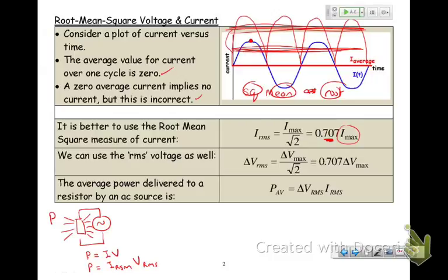that works. So what happens, frankly, is you get used to being able to treat AC circuits like DC circuits as long as you use the RMS values. So you can do a simple circuit with a whole bunch of resistors in it. This is an AC current. How is this going to work? Just use RMS values and it just works out just the same. Sometimes you forget and you don't realize you're using RMS values because all the questions are given in RMS values.